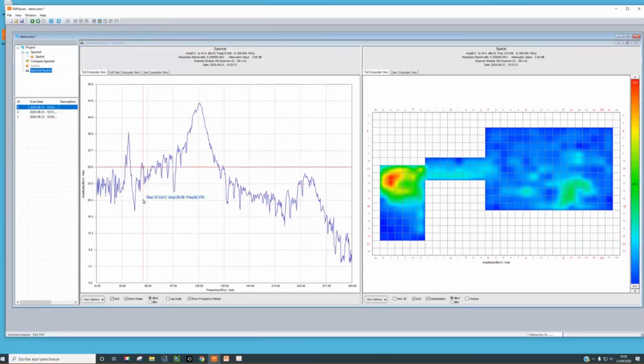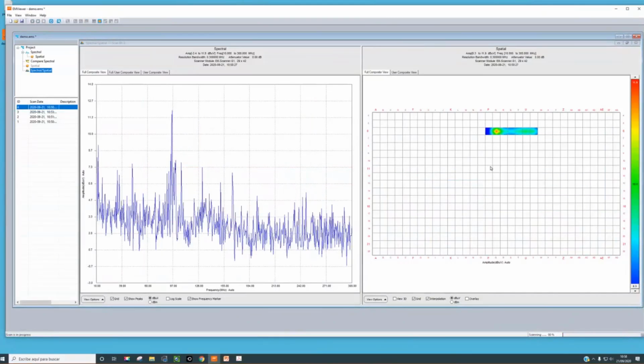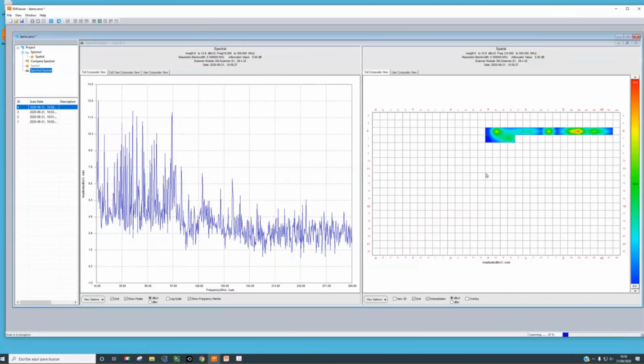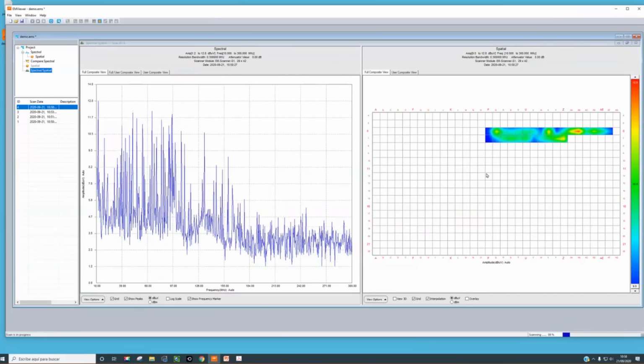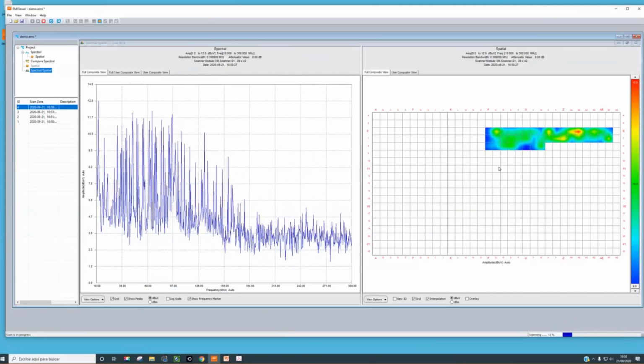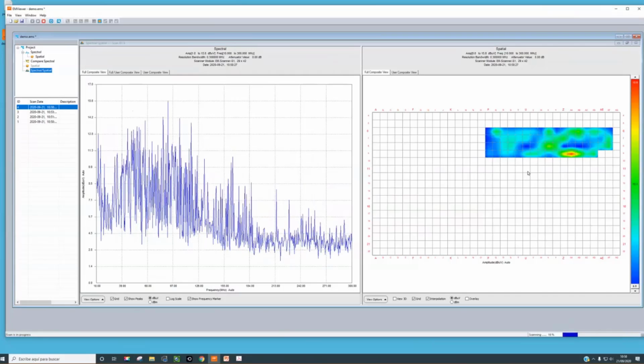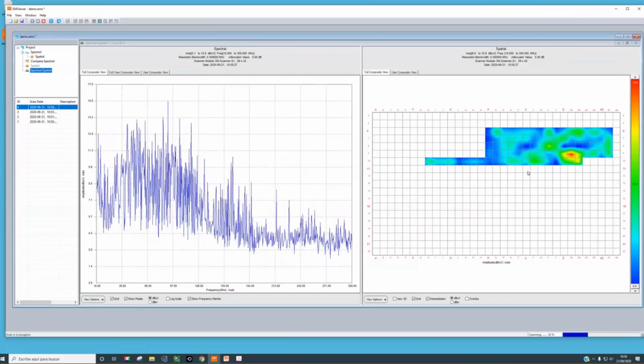Remember that if you have a cable and the 2 wires in the cable are close to each other, usually differential mode currents will not create a problem for you. But common mode currents, the current that goes in the same direction in the 2 wires, have an uncontrolled loop, and around 15 to 20 microamps of current circulating in your cables can create strong radiated emissions. That is why many people typically use a ferrite in cables when they are failing radiated emissions.